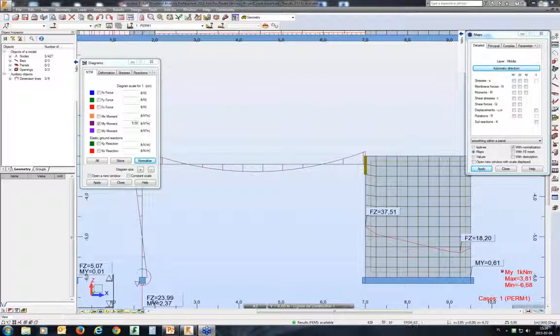Okay, great. All right, next question. What is your recommendation on using kinematic constraints or not? Okay, as I tried to explain, if you, for example, want to reduce the number of elements, the size of the model, like in this example, you want to generate a denser mesh for floors and fewer elements for walls, then you can go for this option.